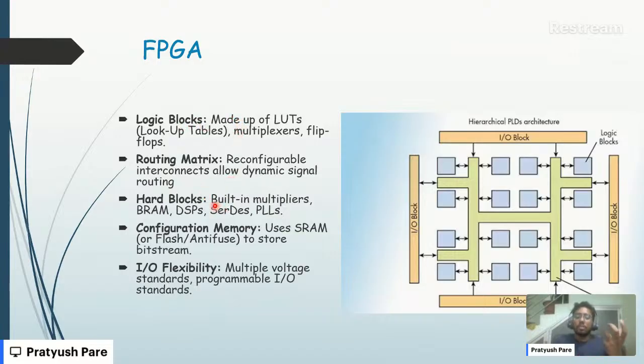These built-in multipliers will be very fast, meaning they are optimized multipliers. Sometimes the synthesis tool might not optimize your multiplier code correctly, but if it uses the built-in multiplier, it will be very optimized. In the same way, there will be different BRAMs, DSPs, PLLs, etc.